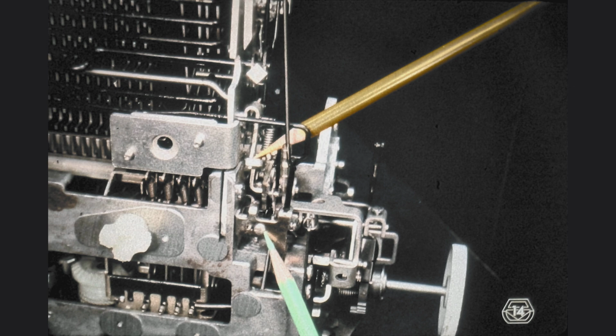We must adjust the amount of wire wound envelope which exists between the point indicated by the yellow pencil and the point underneath the carrier, so that there is no slack in the velocity control cable when the machine is at rest. Try changing the adjustment on your machine, and notice that if you feed too much envelope to the right of the adjustment point indicated by the yellow pencil, the position of the roller on the print cam follower is shifted toward the left.